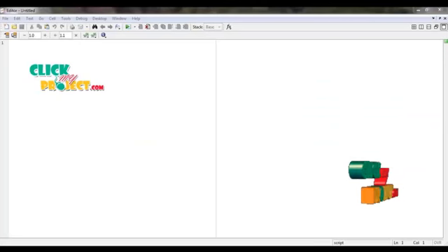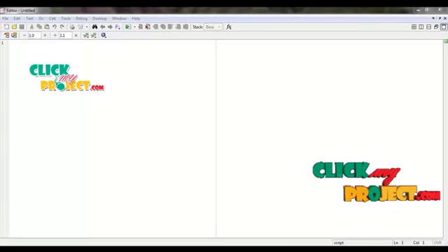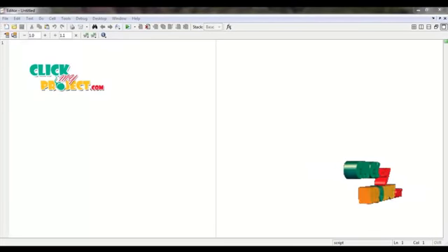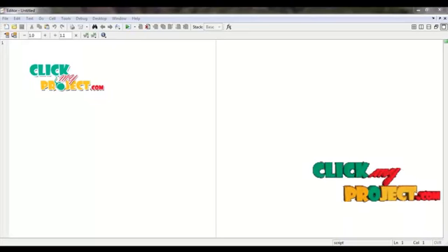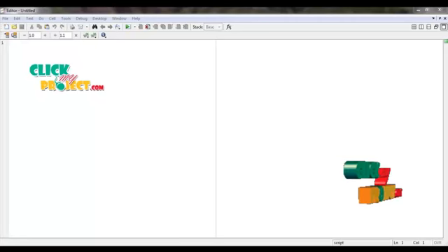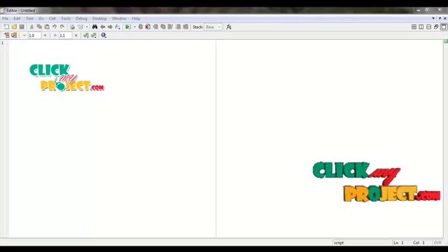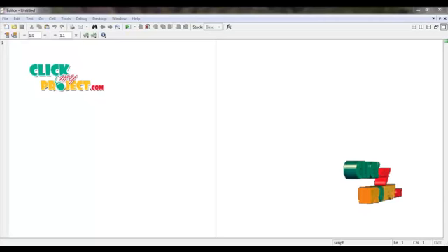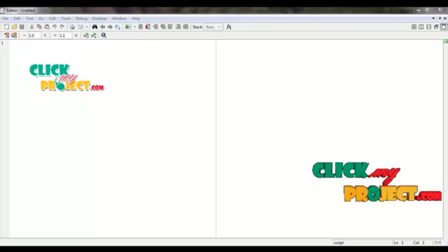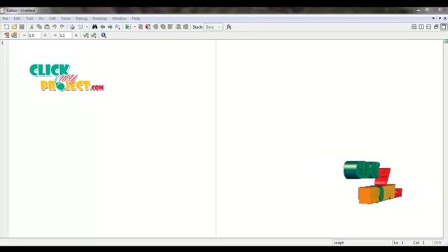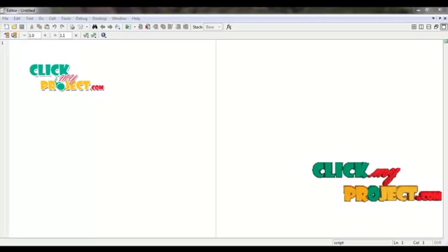Now we see about our model. In the proposed system, we use the PV cell to connect to the grid. Initially we design the PV cell to generate the voltage by different irradiation. The irradiation will be generated by random numbers. That irradiation will generate a random output voltage, and that random output voltage will be controlled by the MPPT controller, and it will generate the pure DC PV cell output voltage.